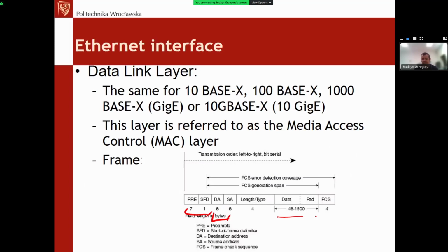So in the case of a microcontroller, if we talk about a FIFO, we need to be able to hold a few frames so that the microcontroller core is able to deduce the validity of the frame, and for example to calculate the CRC, because we've got a 4-byte CRC, called CRC32 here.